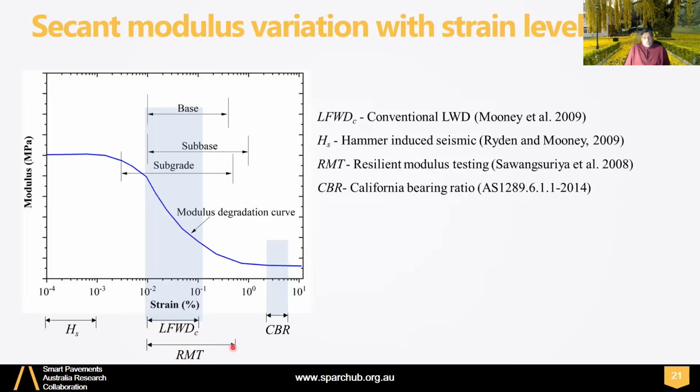So that's also good. CBR, for example, we mentioned in the last webinar that CBR is also kind of a modulus or relative modulus. So that modulus is actually straining soil a lot, 5-10 millimeters, 2.5 and 5 millimeters over a certain length. So that strain comes here, and that means we are likely to get a lower modulus by that method. Although we try to correlate that by multiplying by 10 to get the resilient modulus to be used in design. So that can be understood in that fashion.